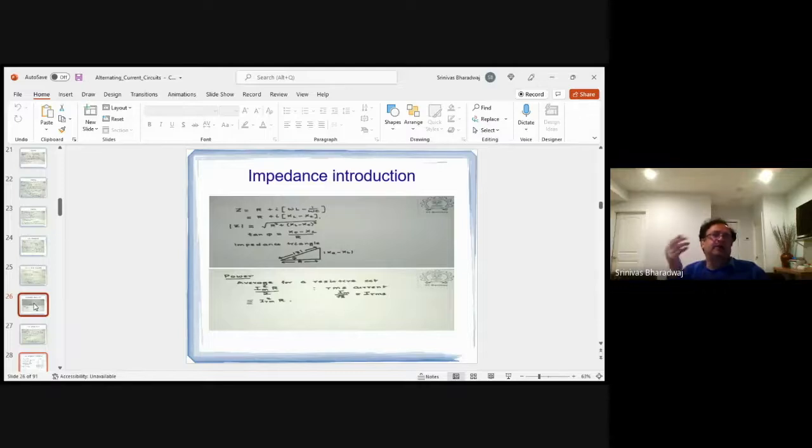So what is the power? IRMS, Im square R by 2. How do you end up with 2? Because it is IRMS by root 2 for I, right? And it is IRMS square R. Therefore, 1 by root 2 times 1 by root 2 is 1 by 2.